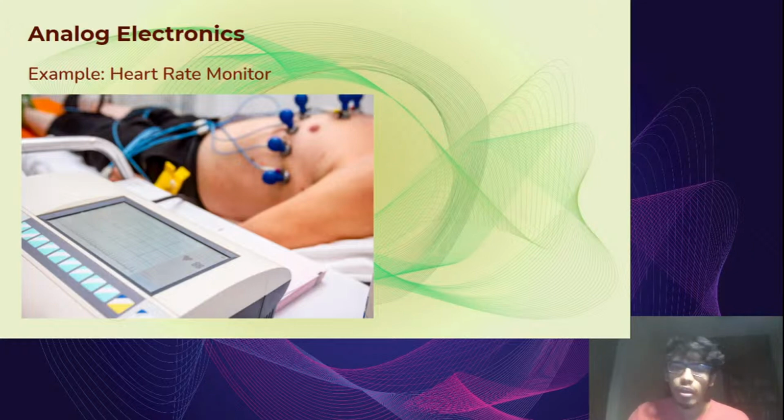Before it is recorded, this is a very sensitive signal, so we have to filter out all the noise. We usually have a filter which removes the 50 hertz noise which is picked up from our mains electronics. And finally, this analog signal is converted into a digital signal using an analog to digital converter.